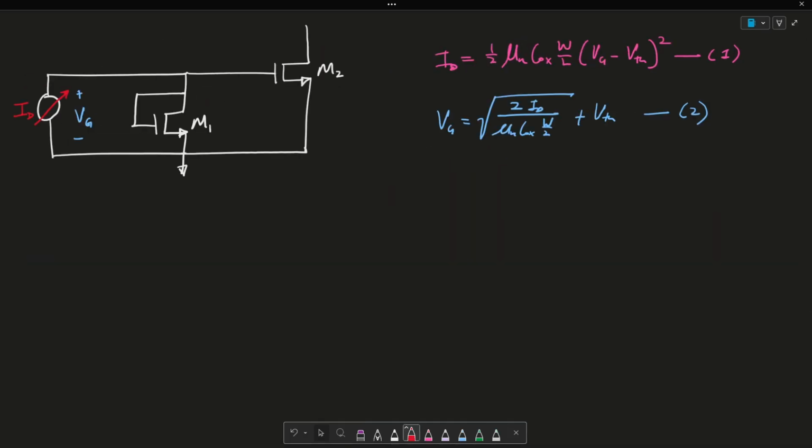Okay, so for the last part of this video, what we want to do is attach our beginning circuit with this NMOS, or this transistor connected here, and we want to derive an equation or see what happens. So let's call this I out here. The first thing we want to note is that VG, so this VG here, is from this node to this node. All right. So this here is VG, and essentially also this here is VG. Long story short, the input to my I out transistor, or my M2 transistor, is VG.